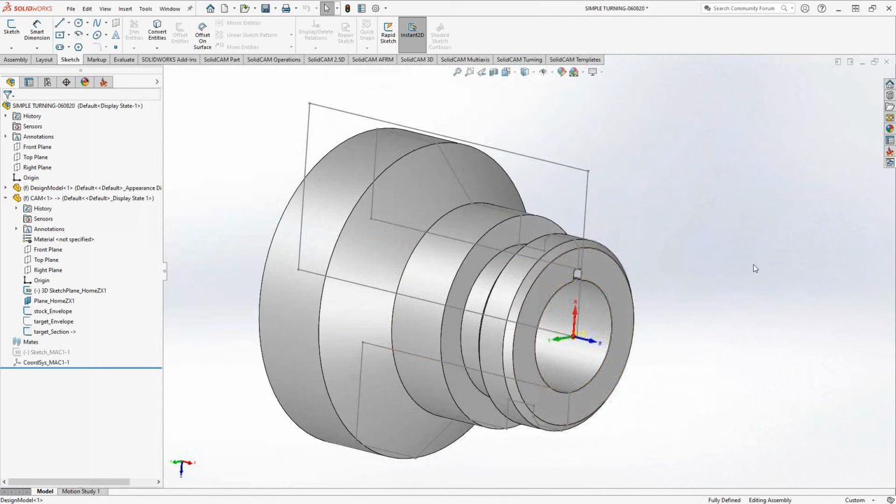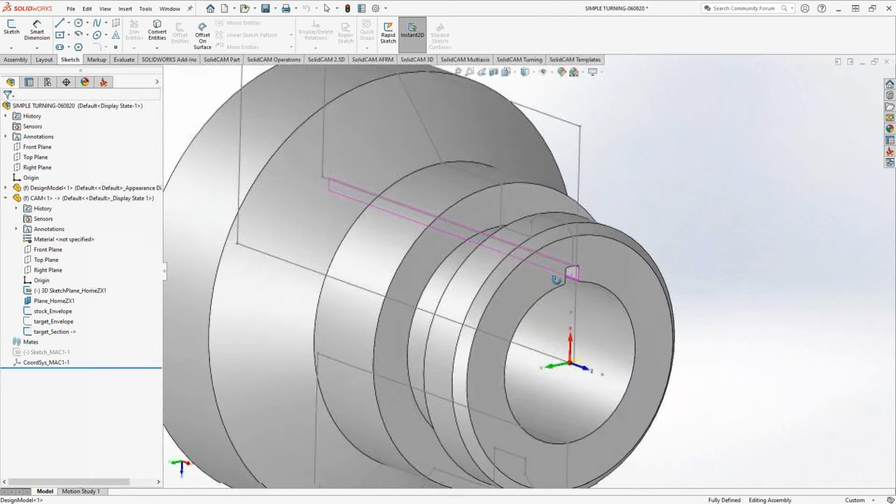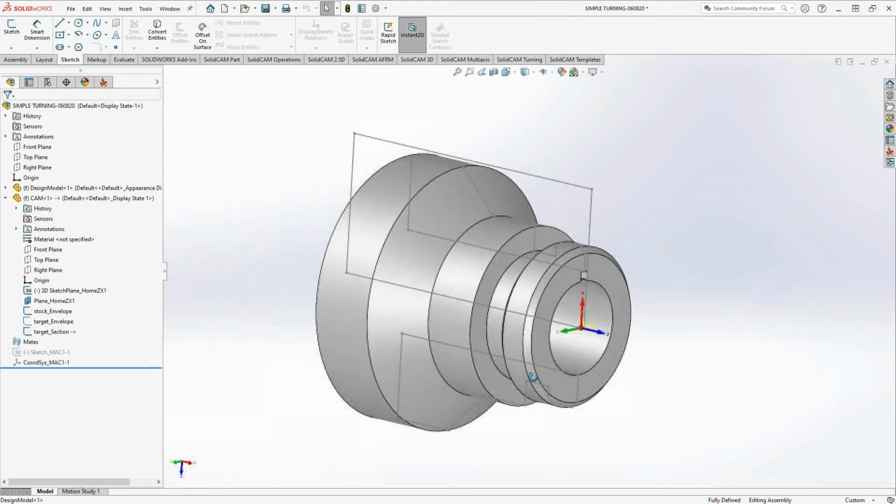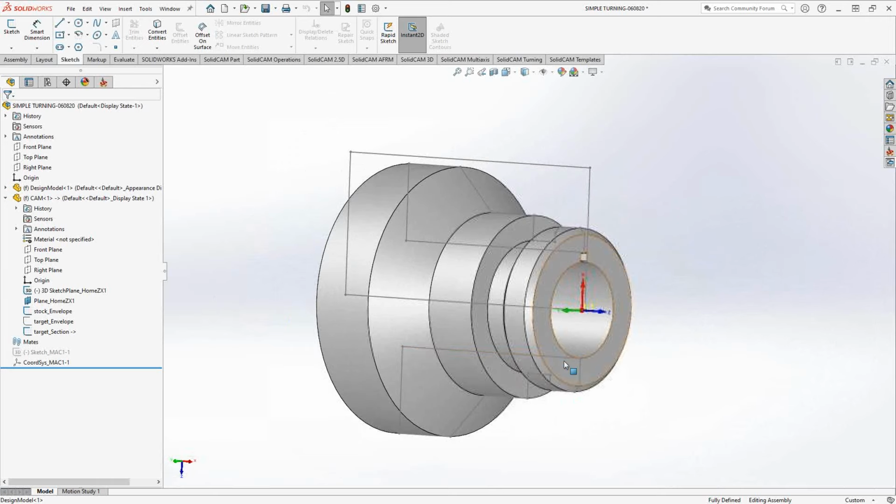And again, that could be useful if you are just having trouble generating that envelope. You can get that cross section straight away. That usually generates an even easier, cleaner cross section profile geometry you can use for your external turning. And then for the internal turning, you can take into account that you have a keyway there, possibly by maybe rotating your coordinate system so that it goes through this way, so you actually get that clean upper half. Or generally, you do have this lower half you can use for your turning as well.